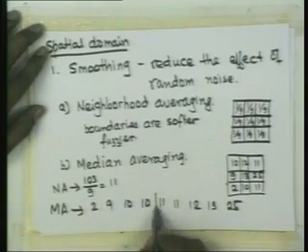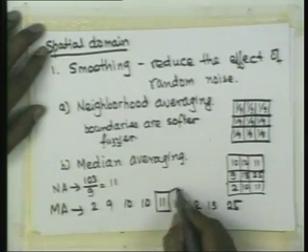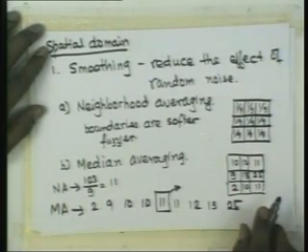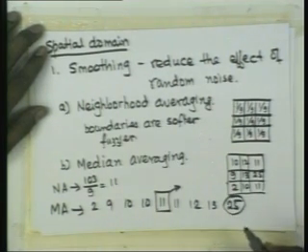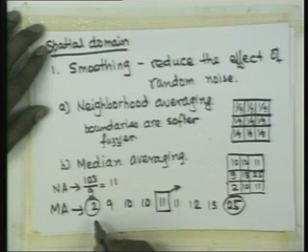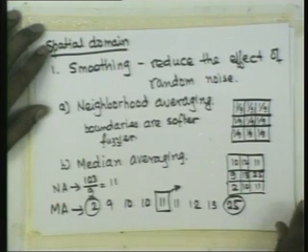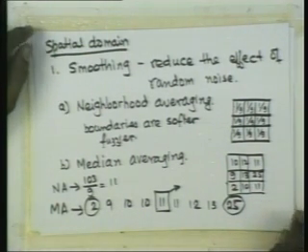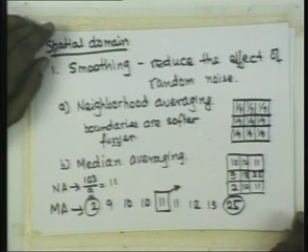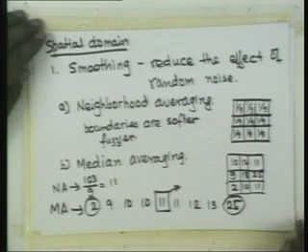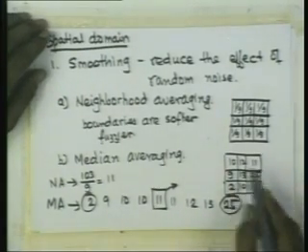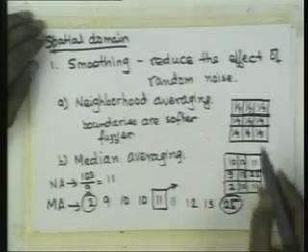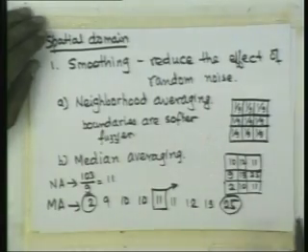So it is the 5th one out of 9, and so this again turns out to be 11 here, right. But you will appreciate that it does not depend on what this value is or what this value is, right. So it gives you immunity from outliers. If some value was very different, then your average does not depend on that. So in many cases it turns out to be superior. Okay, it requires a slightly different type of processing and cannot simply be defined as a mask.